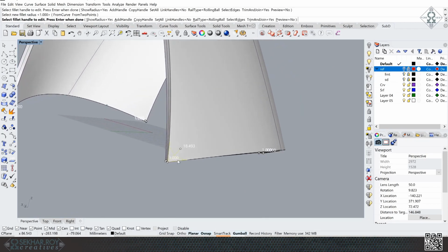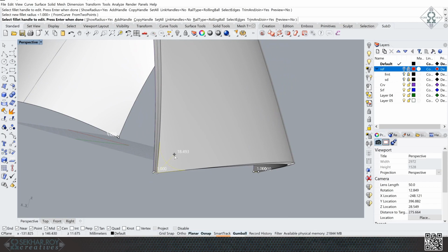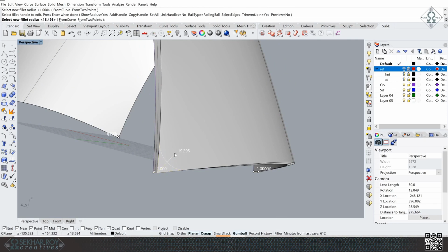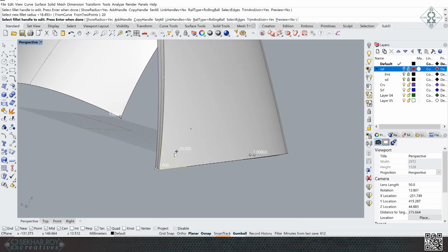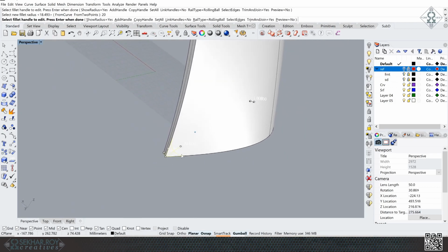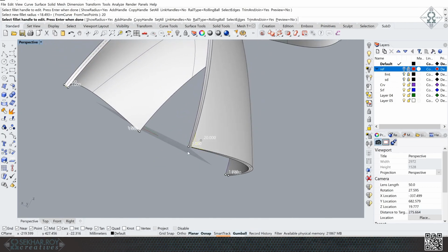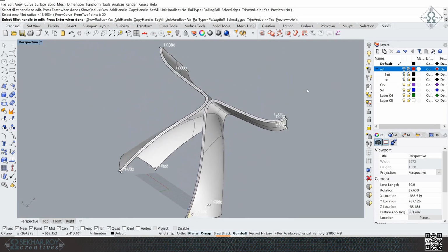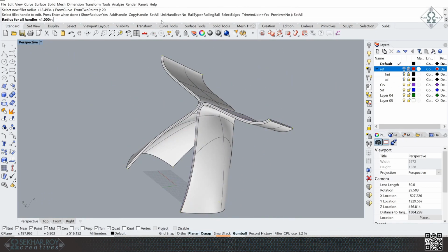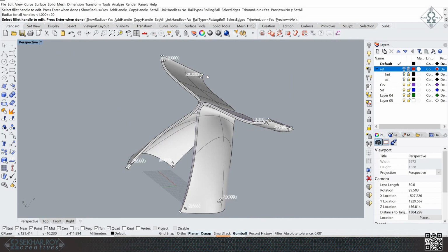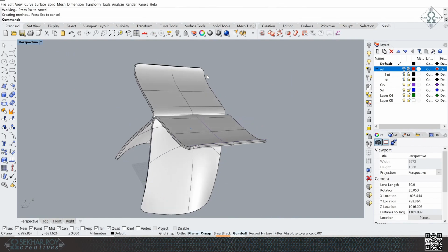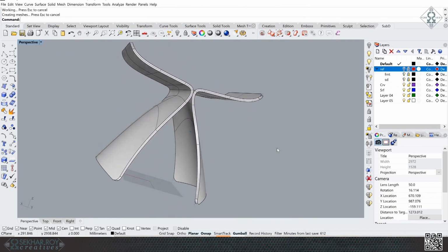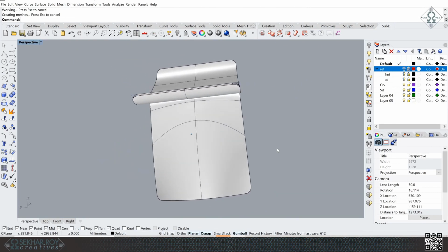I drag that point up to see how much of the fillet I need, so it shows me a number. So if I click here and type 20, it shows me that 20 radius there. So 20 looks good, and I want to apply this 20 on all the selected corners. We go to set all, type in here 20 and press enter, so that rounds those corners on each side.